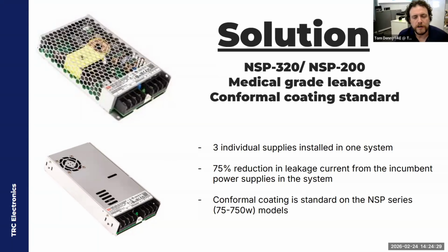So Mike, leakage current. We're talking earth leakage current. So it's based on the capacitance to ground, right? Between the AC input and ground. Yes, actually, the most common point is the common mode capacitors that are usually in the input filter to ground. If you think about it, you have both line and neutral, and the impedance of those capacitors over frequency allows them to conduct to a certain level.